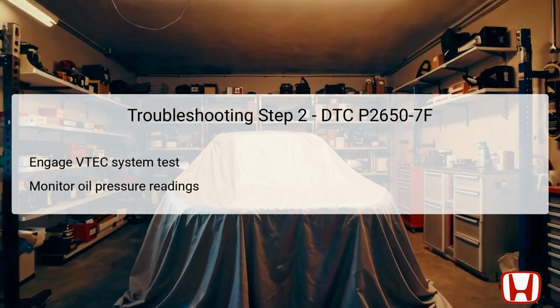This testing procedure involves starting the engine and holding the engine speed at approximately 3,000 RPM without load, allowing the radiator fan to activate before letting the engine return to idle. During this process, monitoring oil pressure readings becomes paramount. The HDS diagnostic tool will display live data relating to the rocker arm oil pressure sensor and the VTEC system's oil pressure. Proper analysis will reveal if the oil pressure is above the specified level of 49 kilopascals, 0.50 kilograms per centimeter, 7.1 psi, when the VTEC solenoid valve is activated.